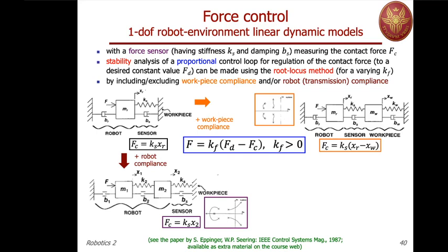Of course, the total sum remains the same, so M1 plus M2 is equal to MR. Now you're pushing on the first mass, which represents the motor position, with x1. K2 represents the stiffness of the joint, or at this level of this monodirectional dynamics. And indeed when K2 goes to infinity, you recover the previous situation, so the two masses become the same mass.